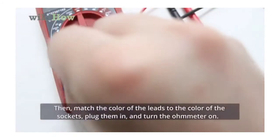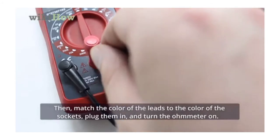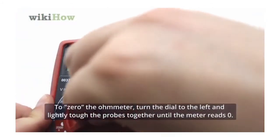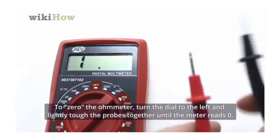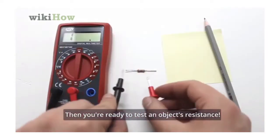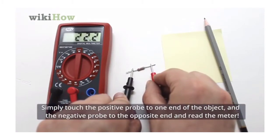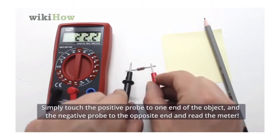Then match the color of the leads to the color of the sockets. Plug them in and turn the ohm meter on. To zero the ohm meter, turn the dial to the left and lightly touch the probes together until the meter reads 0. Then you're ready to test an object's resistance. Simply touch the positive probe to one end of the object and the negative probe to the opposite end and read the meter.